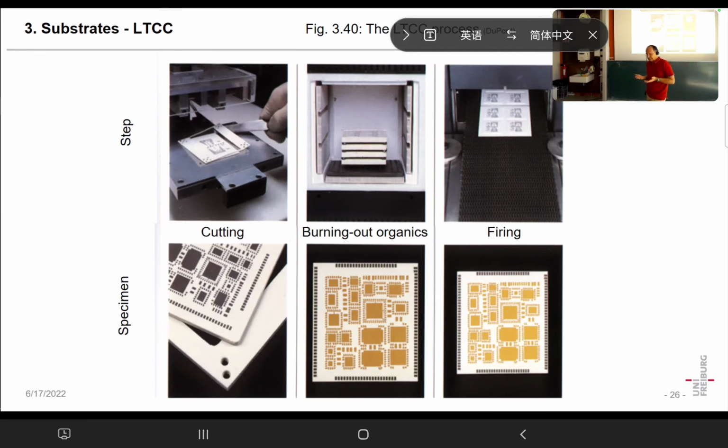And in that way, that shrinkage must be precise. So again, that requires precise control. If we do wire bonding, it's not a problem, because a modern wire bonding machine, once programmed, is clever enough to look for the bonding site, not where it is programmed, but in the area where it is programmed.